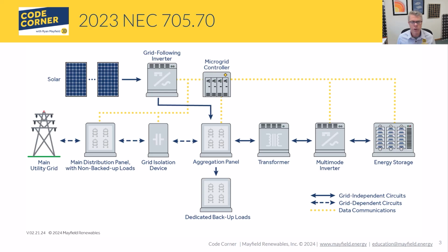This is a well-known thing for PV systems. These are built into our PV-only inverters. It's really simple. The grid goes away, the PV inverter stops operating, no problem. With our microgrid systems, it becomes much more complex because we've added storage into the equation, and we absolutely want our systems to operate when the grid is gone. That's one of the big reasons why we do microgrid systems, is to back up loads. So you are up against having to find a grid isolation device.